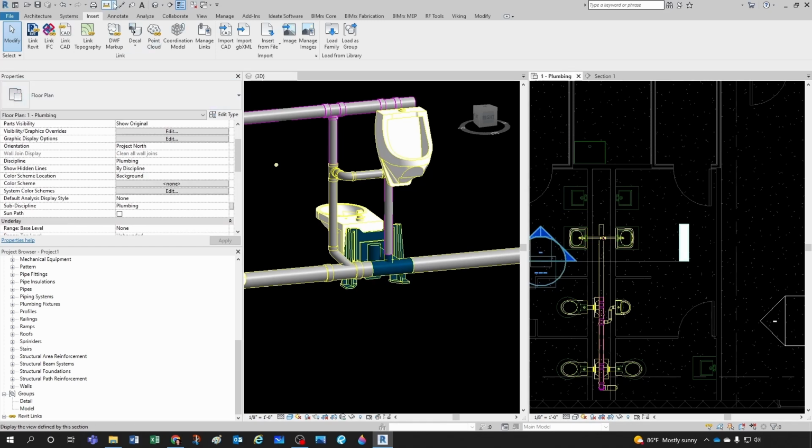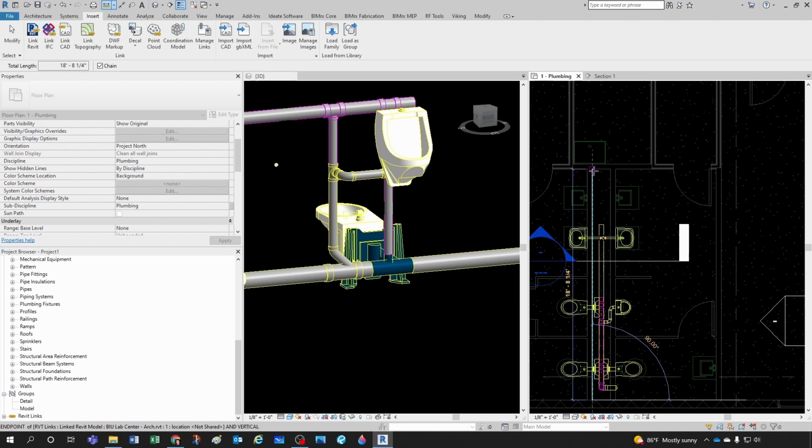and all I need to do is to make sure, see, like if I measure from here to here, I have 18 feet, right? So in 18 feet, I'm not even dropping 3 inches. So if I measure, say, from here to here, I have about 18, 19 feet, and 19 feet at 1/8 of an inch of slope per foot is not even 3 inches.